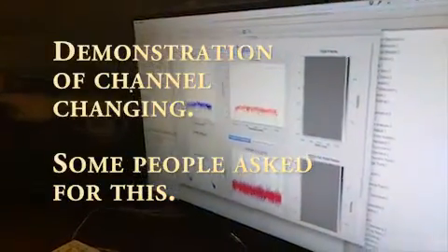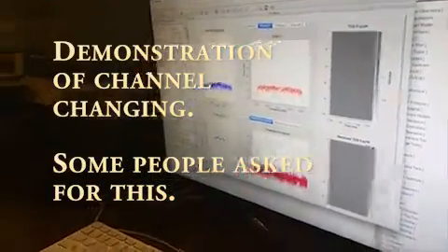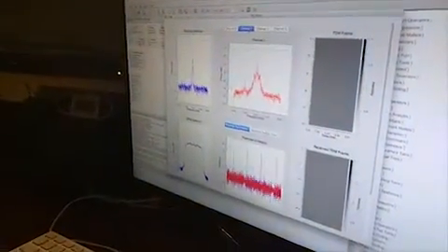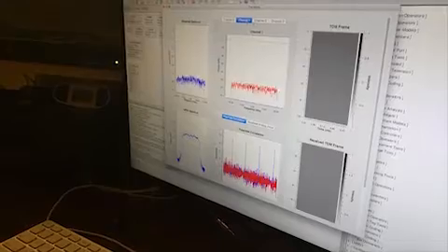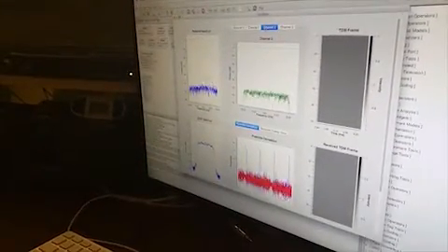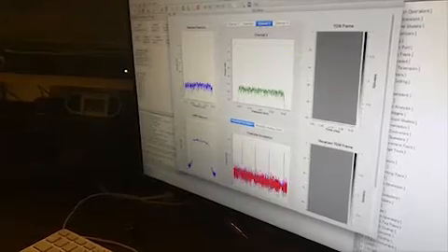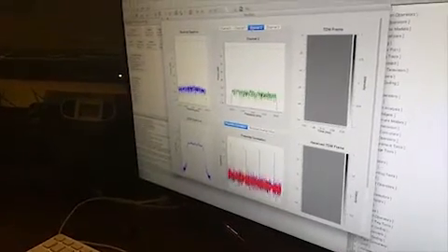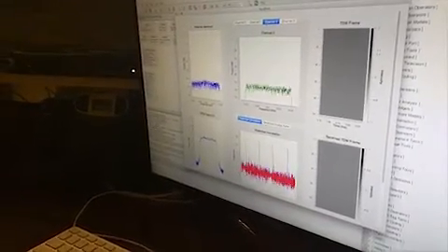So there's receive audio. Channel 1 is 146.025. Have to defeat the radio's repeater shift. So there it is. That's great. I switch channels, and it doesn't show up until I change frequencies to match. Now it does show up.